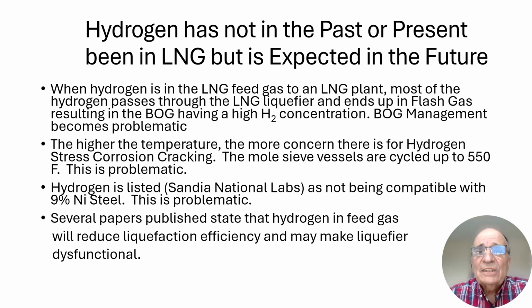That's where hydrogen reaches a stress point in the metal, whatever the material is. Typically it's metal, but it reaches a stress point in the metal, becomes monatomic hydrogen, migrates between the grain boundaries and into the metal, meets up with another monatomic hydrogen atom, and becomes diatomic hydrogen, which now produces a bubble or a gap within that metal, which becomes a stress concentrator.